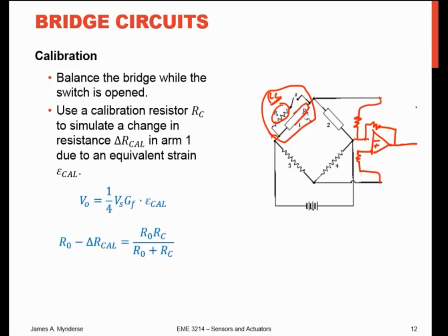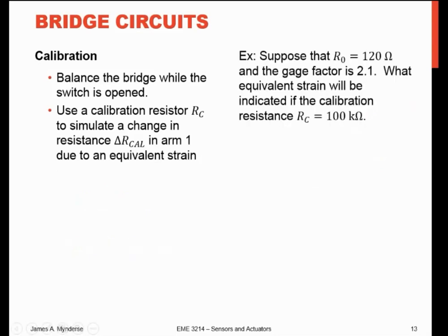And it's a minus because I can't put a resistor in parallel and make it a higher resistance. We can only calibrate in one direction. But if I take my equation for a parallel resistor here, I'm going to let this term equal X just to save some writing. I can rearrange that to say... well, I'm not going to do that. I'm going to do that on the next slide, because that's exactly what the next slide asks us to do.